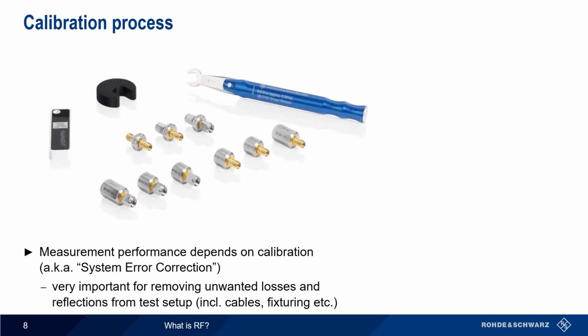Typically, VNA calibration involves connecting test standards representing a short circuit, an open circuit, and a 50 ohm load or match to each test cable as prompted by the calibration routine, and then inserting a through standard to the end of the two test cables.